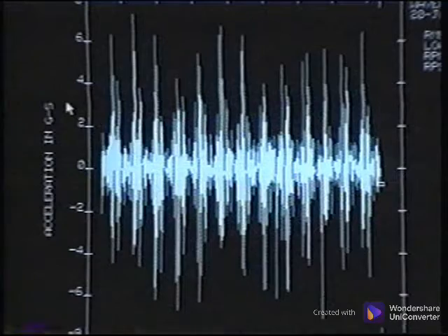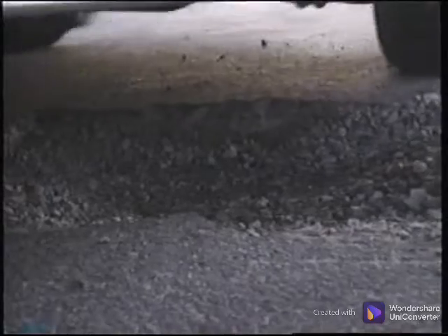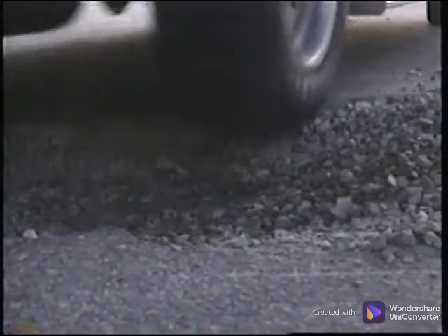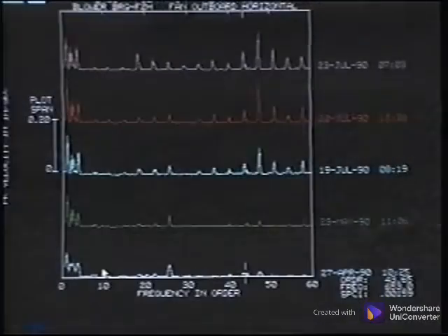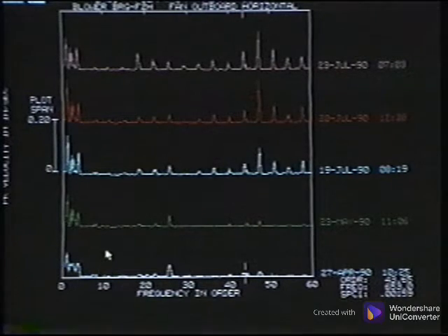Here again, we see that it is important to store the waveform in acceleration, even though the spectrum is stored in velocity. There is incredible impacting with up to 14 G peak-to-peak swing. Note the high levels as the rolling elements impact the defect and then smooth out on undamaged surface. This can be compared to an automobile tire impacting a pothole, coming back out and settling down as the pavement is smooth again. The historical spectral data for this bearing over the previous months looks like this.